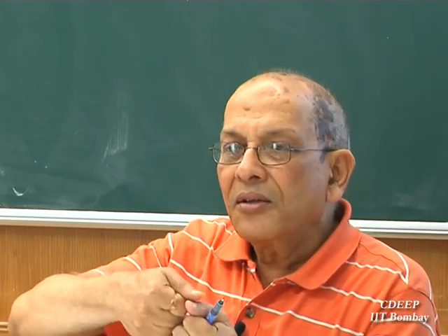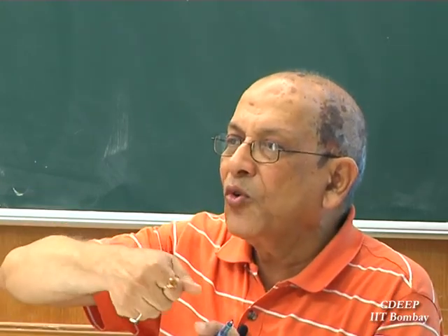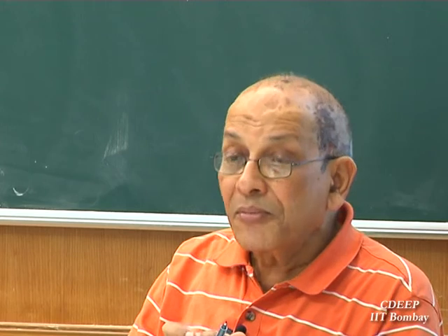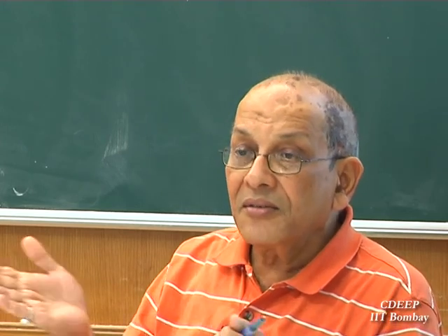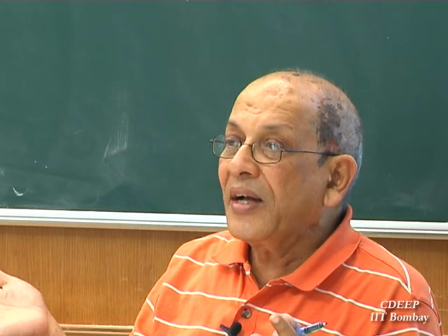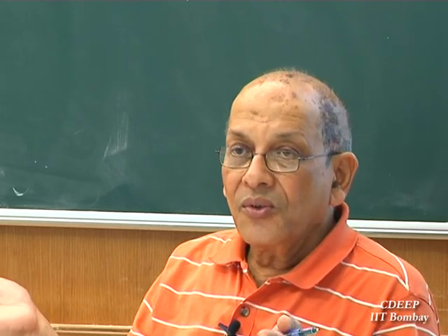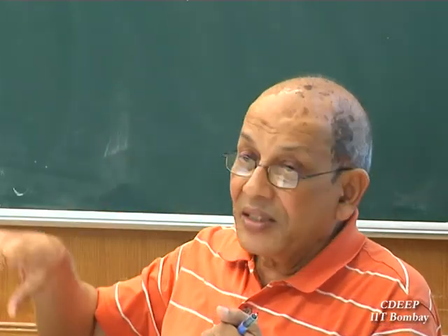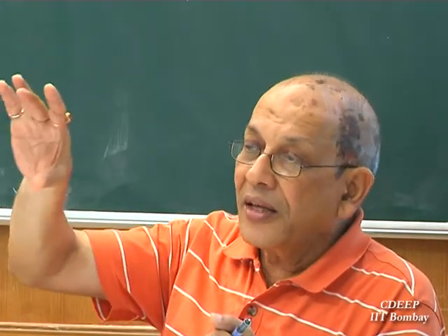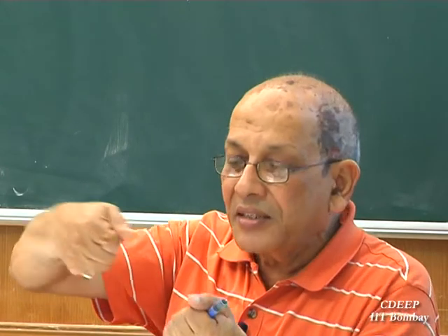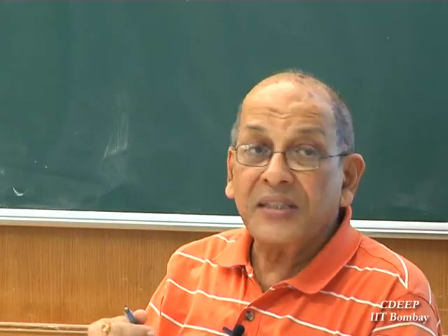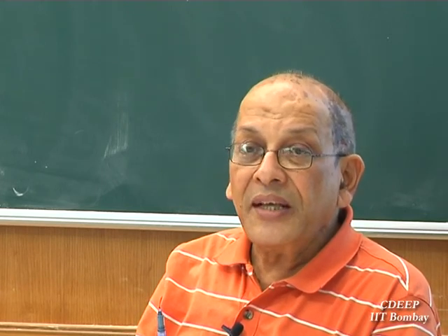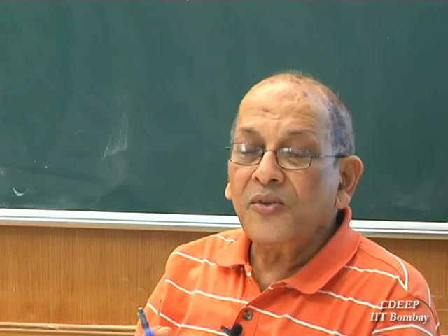So what will happen? Material along that will fail. It will go into plasticity. We don't want material to fail. So it helps us to design the member. You should know in advance what is the maximum value. Unless you know, how will you fix? So you have to change the dimensions of the beam and then analyze again, so that the maximum value reduces and becomes less than the yield value of the material. Otherwise stress will exceed the yield value, and obviously it will go into plasticity.